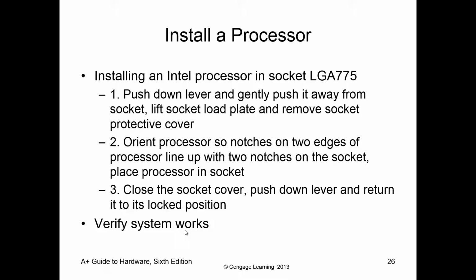Here are the instructions once more for a different type of processor. But here, still an LGA, so that means typically no pins. But again, you read the documentation, you line up the processor, you install it without doing any pressure, and you lock the lever.